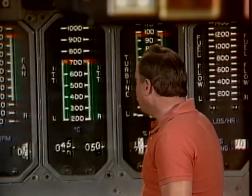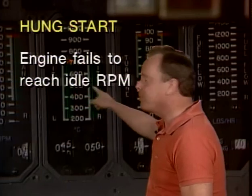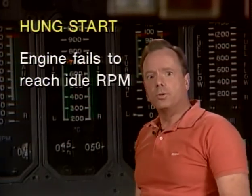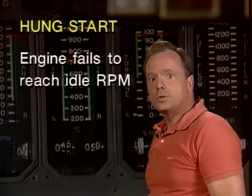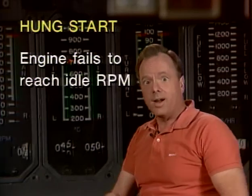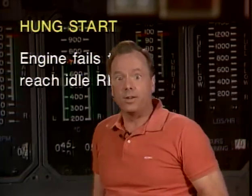Now, what is a hung start? Well, a hung start occurs when the engine fails to reach idle RPM. A general cause of a hung start is the starter cutting out too early, and if the starter disengages too early, then the engine might not reach idle RPM. It'll just stay right there and not get there. So the starter should not be disengaged, either manually or by itself, until you get to idle RPM.